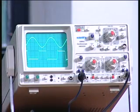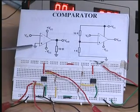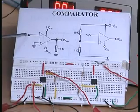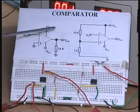Now I want you to look at the second circuit. In the second circuit here, you find the plus input, or the non-inverting input, is connected to ground, and to the inverting input you are going to connect a sine wave. At the output I have put a simple load resistor of 10 kilo ohms and am monitoring the output. You know what is going to happen.